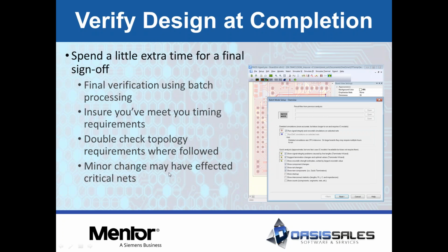And then of course at the very end, after the board layout's been done, you may not be the guy that's doing the actual board layout. You may have tried to convey as much as you can to a services company in what to do in the design, but they may not follow everything that you've suggested. So bring the board back in. You can do simple verifications using a batch process in the board sim tool. I can run, check every single net on the board actually very quickly and find those ones that are suspects and then go back and check them individually.